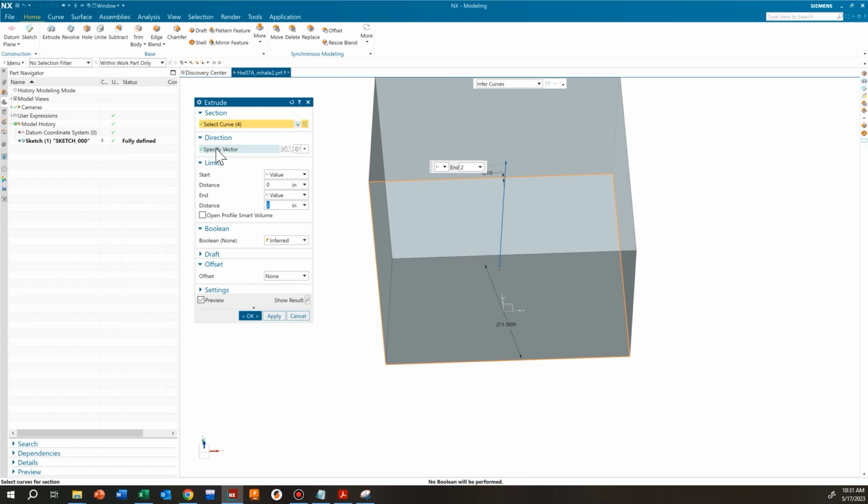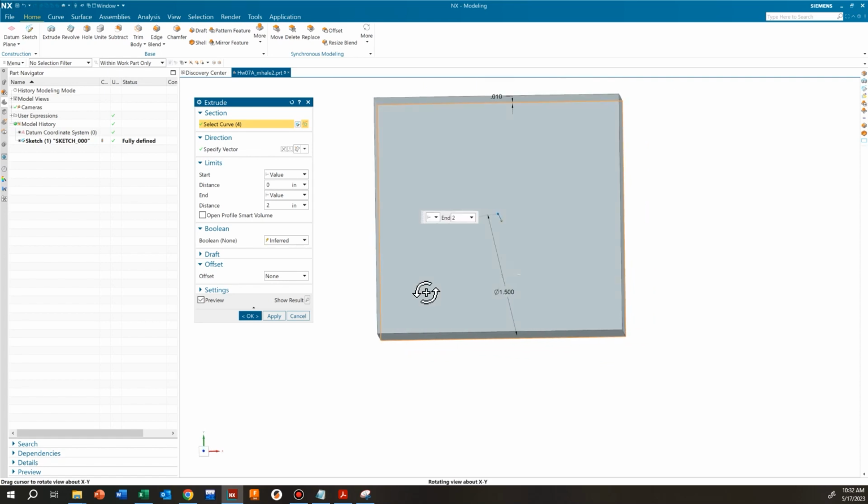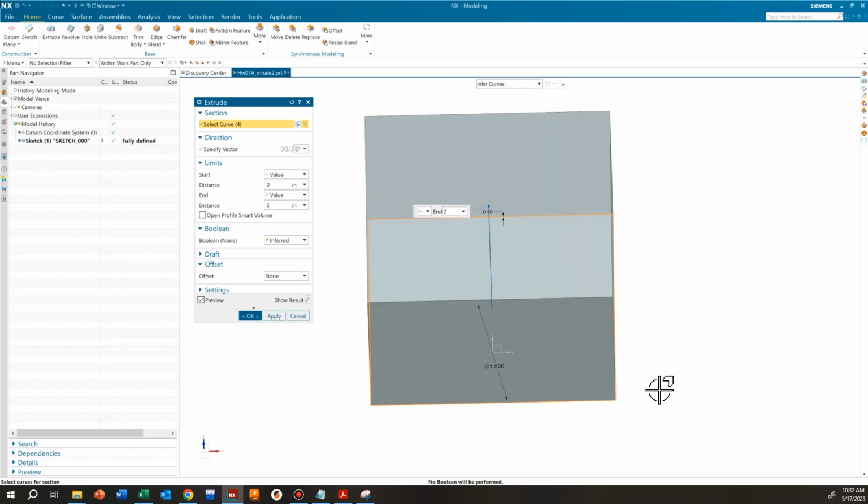Now there's many ways to make this box. This is just one method that I'm showing, and I'm showing it specifically because it's a different way of doing it that we haven't looked at before. And the thing that we haven't looked at with the extrude command is these offsets. Similar to when we created the offset to create the boundary, what the offset in the extrude command does is it takes our 3D geometry that we've made and offsets it from the sketch boundary.